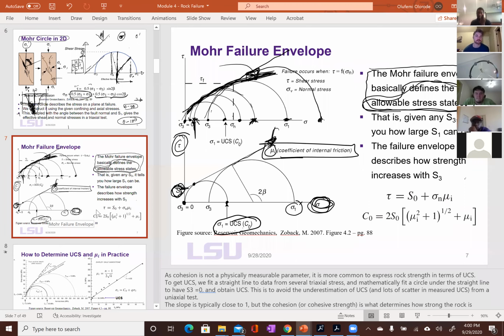There is a third type of strength, which is the frictional strength of the rock, which will be the resistance of the fault block to slipping across its surface. That's the one I just showed, which we'll get to later. So we're talking about the sliding of the fault blocks across the fracture, but we assume that the fracture surface was already there in the rock.